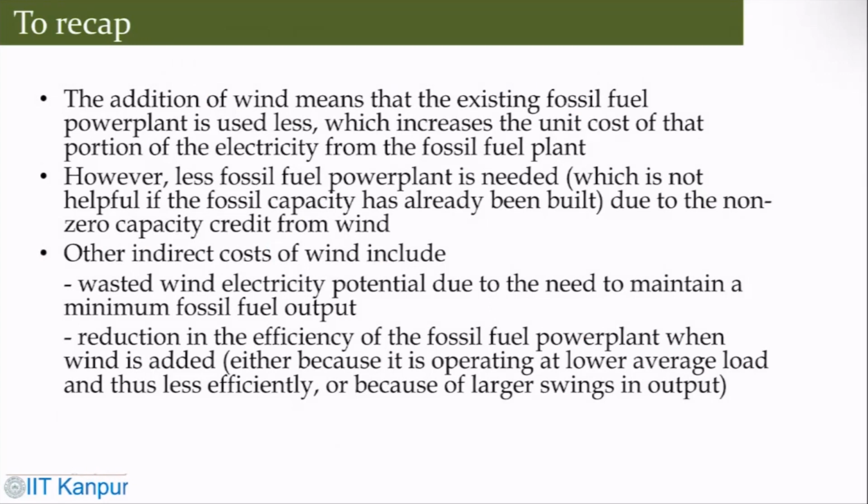However, if you use less fossil fuel power plant due to the non-zero capacity credit from wind, other indirect costs of the wind include wasted wind electricity potential due to the need to maintain a minimum fossil fuel output, and reduction in the efficiency of the fossil fuel power plant when wind is added, whether it is operating at lower average load or less efficiently, or large swings in output.